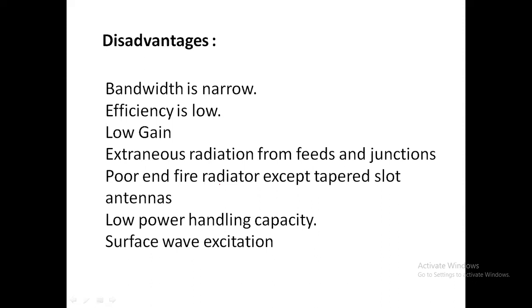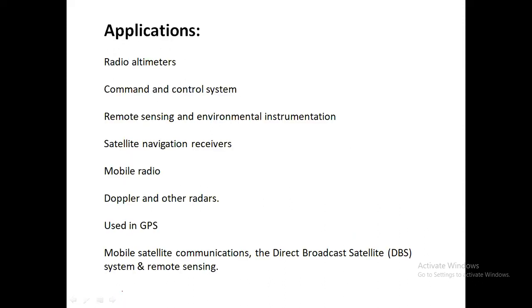And disadvantages-wise, straight away we can say we cannot increase the size or dimensions of the patch, which leads to loss of radiation and efficiency reduction. The same things I have highlighted here, where the bandwidth is low, which leads to low efficiency and low gain; all these things will be happening. And mainly because of the surface waves, which are not needed, will be higher if you have different types of dimensions for your patch antenna.